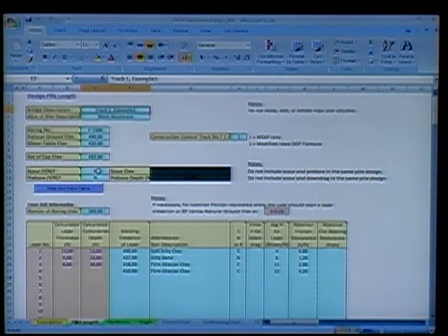All right, so you can handle scour in the spreadsheet. You would say, yes, I have scour, and my scour is down to this elevation for the 100-year flood from the hydraulic data. You can also add pre-bore, which for a lot of our bridges is 10 or 15 feet at integral abutments. You might try to go a little farther if you have down drag, of course, because you're trying to get through those layers to get as little down drag as you can. But there are limits to how far you should do that, because you might buckle your piles, of course. So there's recommendations for that in the bridge manual.